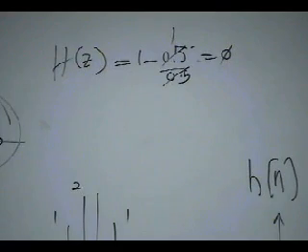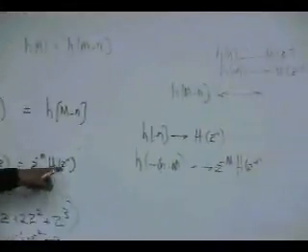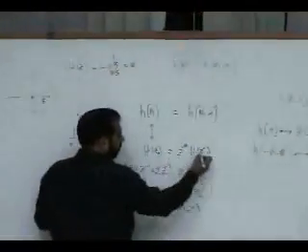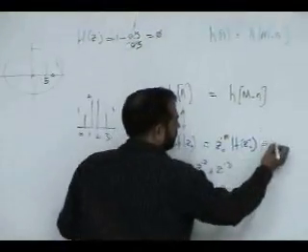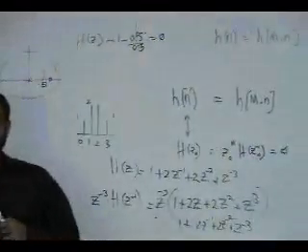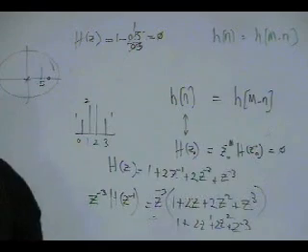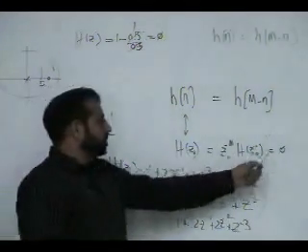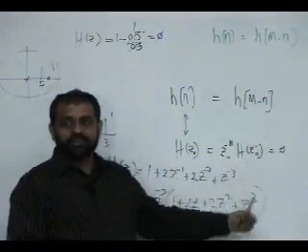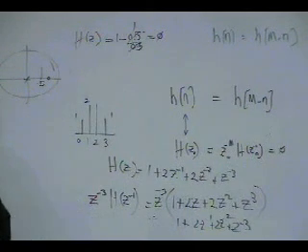So this says that it will obey this. It means a 0 of this will also be a 0 of this. Okay? This is important. For a linear phase, if z naught is a 0 of the system, then 1 over z naught will also be 0 of the system. This is because of symmetry.